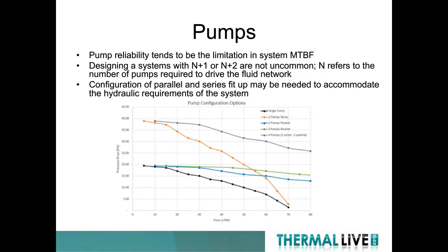So talking about pumps, the pump reliability tends to be the overall system MTBF, mean time before failure, limitation in these systems. As a result, we see many customers designing the system with an N+1 or N+2 requirement, where N refers to the number of pumps required to drive the fluid network. So this is a way to add redundancy into the system.